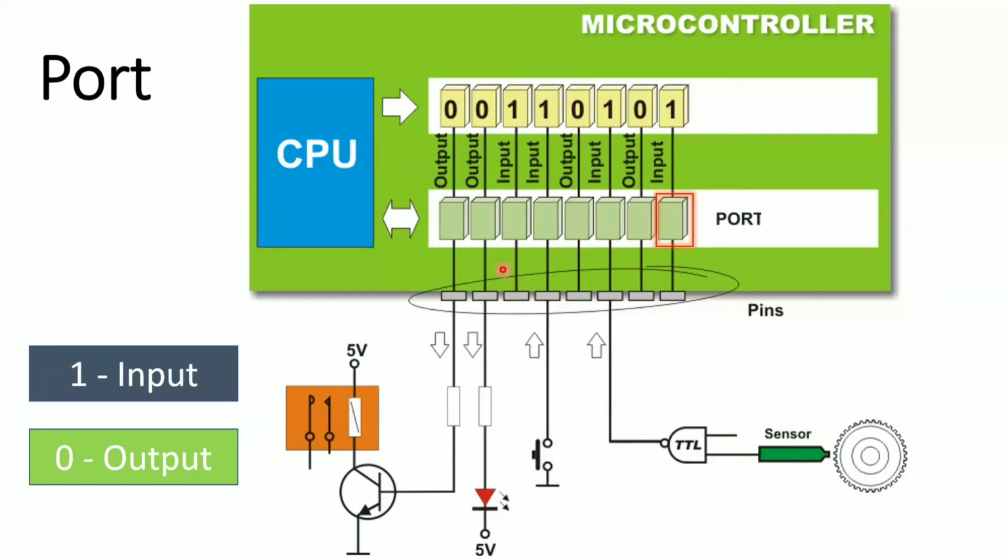And what are the output devices you can connect? You can connect actuators like a relay. You know relay, right? It controls the current of large appliances with the help of a small current. You can connect LEDs, and you can connect displays like the 7-segment display. Yesterday we saw the 7-segment display in the addressing modes class. We can connect an LCD display also, and we can connect motors. These are all your output devices, which you can connect to the particular port.